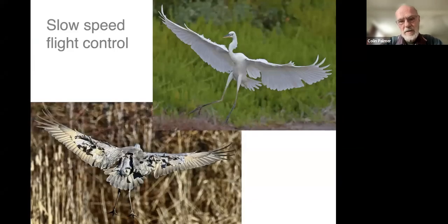The other aspect which needs a bit of thought is landing. Because again, you're coming in fast, so you're going to break something. And birds, they can't change the camber of their wings, so they can't change the amount of lift that the wings produce in that sense. So what they've done is they've evolved a number of passive systems. And you can see on the egret there on the top right, all across the leading edge of the wing, feathers are popping up. And they're from underneath the wing, and they're like flaps really, and they are having the same effect of increasing the camber, which is what aircraft do.